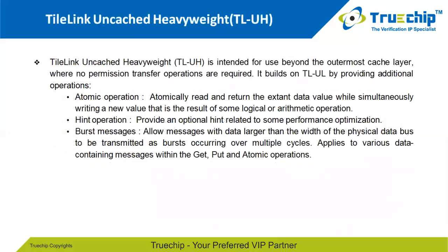Moving forward with the TileLink Uncached Heavyweight. TL-UH builds on the TL-UL and provides 3 additional operations: the atomic, hint, and burst operations. Atomic operations access memory and perform arithmetic and logical operations to change the value of the data in the memory.